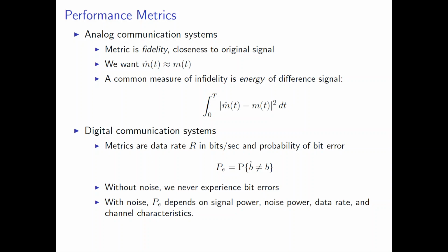Can you use this for a critical Internet of Things application as an engineer? If your application is very sensitive, very critical, you need to have 1 over 1 million, 1 error in 1 million bits. So this 1 over 100 is not good. It depends on the application. But if you are using it for voice communication, it's fine, maybe.